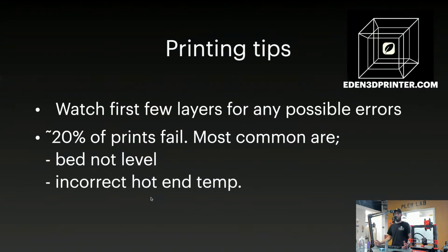Just stick around for the first 2 layers and make sure that it's sticking around. The first layer usually goes slow, but stick around and make sure everything is sticking to the bed, laying down properly, and not going to move.